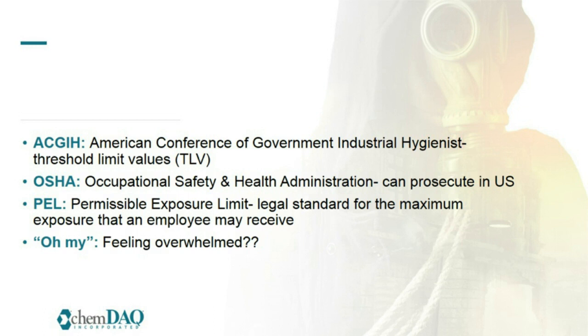The first PELs were created in 1971 and were taken from the ACGIH TLVs, since they had already been adopted as a federal standard in 1969 as a part of the Walsh-Healey Act revision, which then brings us to PELs, P-E-L, Permissible Exposure Limit, the legal standard for the maximum exposure that an employee may receive. For chemicals with no PEL, employers should reference the ACGIH TLVs and the NIOSH recommended exposure limits, as